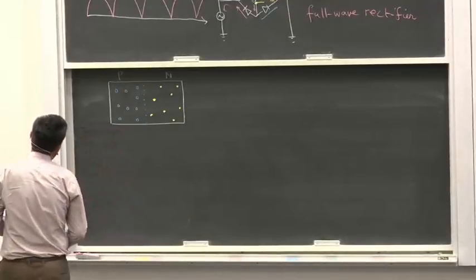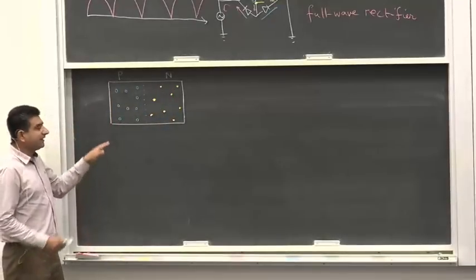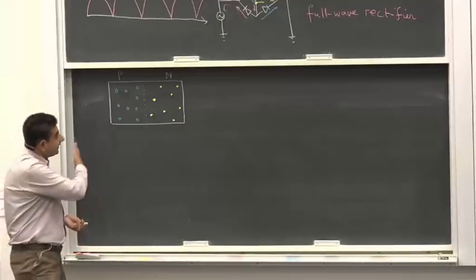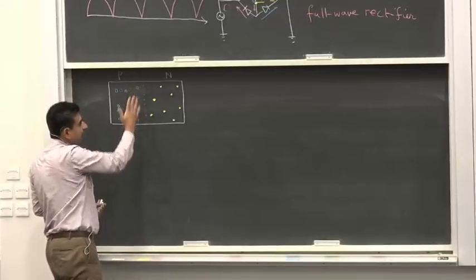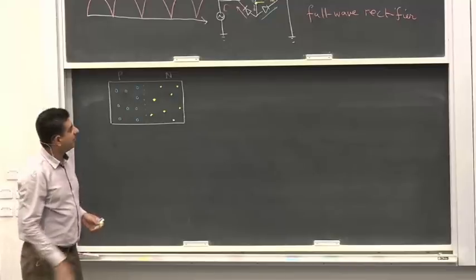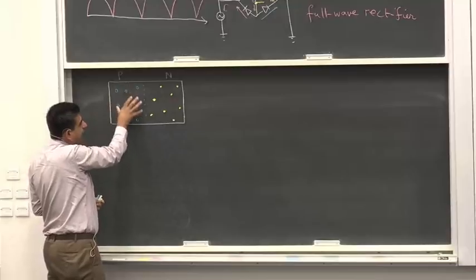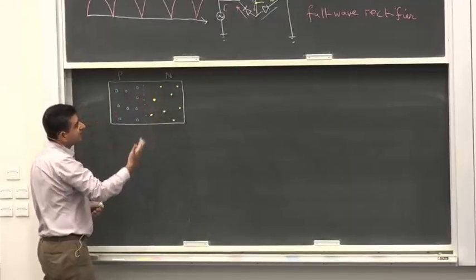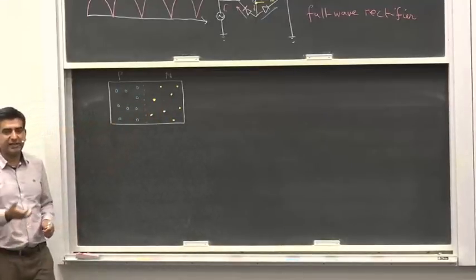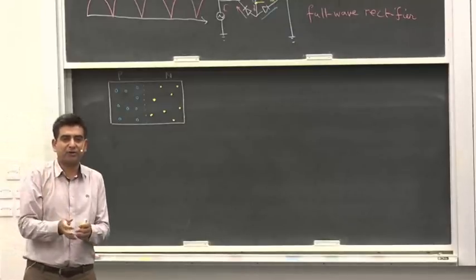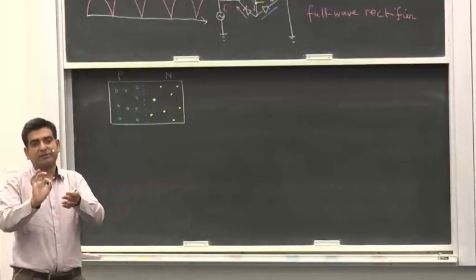Now there's a higher concentration of electrons here and a higher concentration of holes here, but when I give you the diode, this is not the exact concentration. This junction has been formed, and we observe that this is like a compartment full of electrons and this is a compartment full of holes. The electrons must have the ability to diffuse out of this compartment because of the concentration gradient. It's just like opening a perfume bottle. There's a concentration gradient of the scent molecules and they're going to diffuse out of the atomizer of the scent bottle.